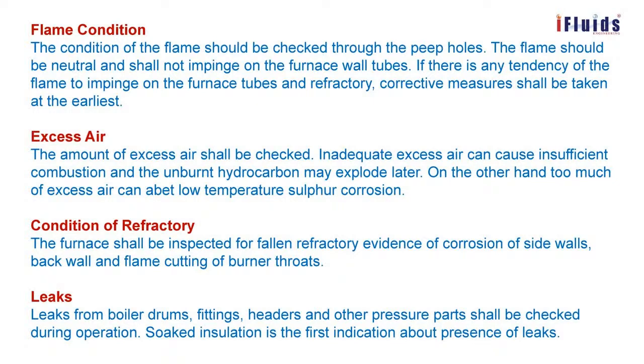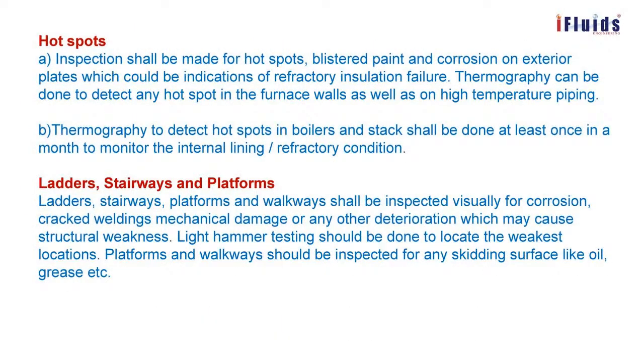Leaks from boiler drums, fittings, headers, and other pressure parts shall be checked during operation. Soaked insulation is the first indication of the presence of a leak. Hotspots are nothing but removal of debris or refractories. If the refractory falls down, there is a possibility of the flame or the combustion zone flue gas touching the outer surface of the frame. In that case, it will create a hot surface there.